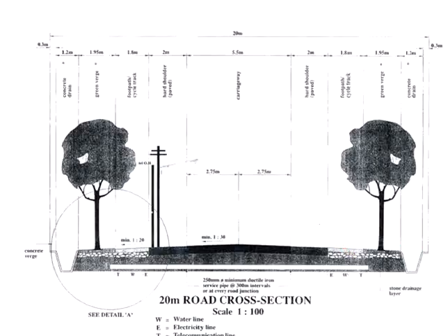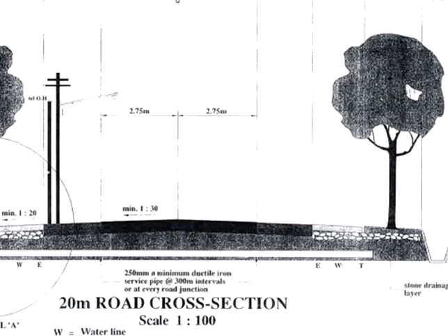Curb may be provided for the safety of the pedestrians using the footpath, especially when you're designing your road section to have a smooth surface between the pavement and the footpath. By having a curb here, probably this will be safer for the pedestrians walking along the footpath. Again, in the case that the curb is provided, you need to provide openings for the water to flow into the drain.